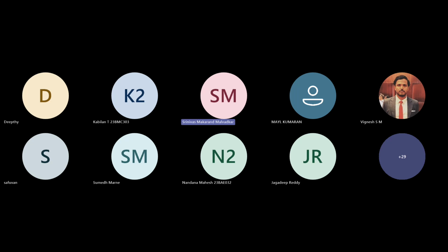Also, sir, while doing the setup, you have given a pressure outlet to the external face of the spherical bound domain. So, is there any inlet face, or only an outlet face you have given? No, only pressure outlet is given. There is no inlet. The flow is happening completely due to the rotation of the propeller. Okay, sir.